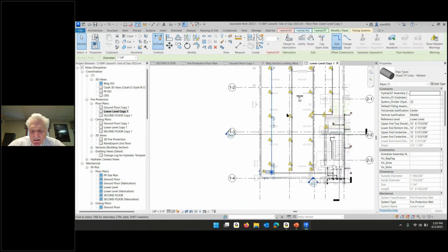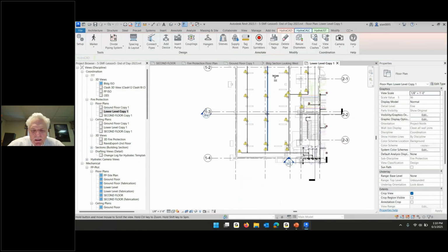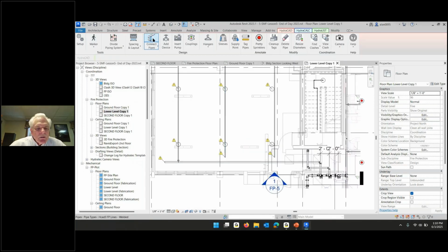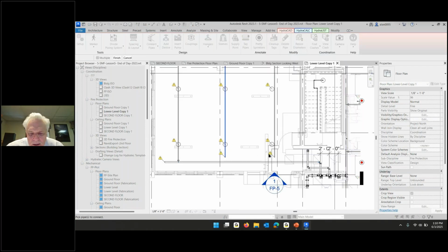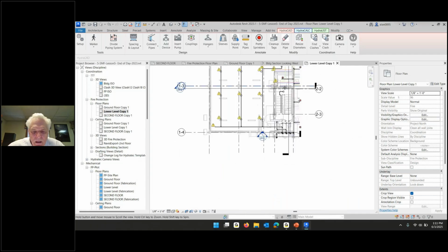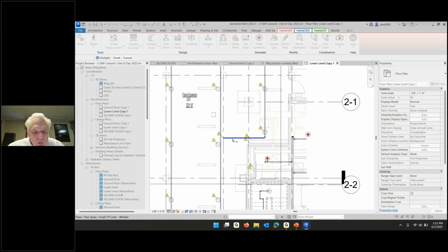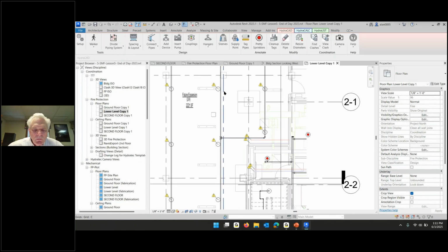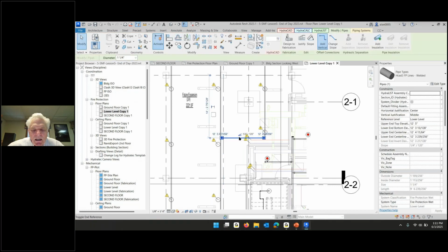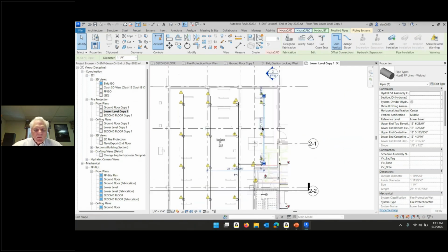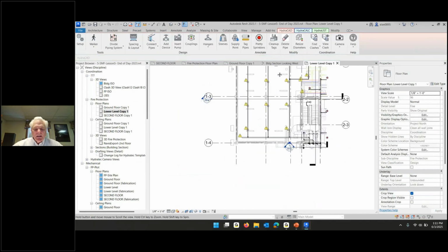And now I'm going to do the same thing with these other 2 branch lines, and I'll do them both at the same time. So connect pipes, raise it in before you connect it. So raise it to this, that pipe, and finish. And then raise this pipe. I'm going to start over, connect pipes, raise into this pipe, this one, and finish. And now this guy's still 1/4 from before, but this guy's still 1/2. And now I can connect the heads.